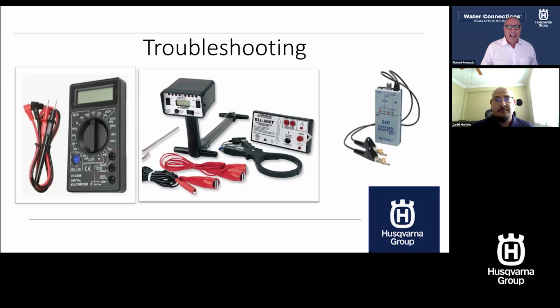So, okay. And then I think too, Danny, do most of the wire problems or shorts occur right around the valve or sometimes other places? So the majority of the time, what you come across is improper parts being used. For example, wire connectors. We've probably all seen this. I've got one here, a little wire connector designed to be used indoors in your home inside an electrical box. Oftentimes we see that.